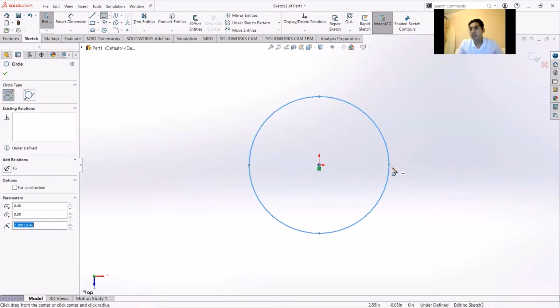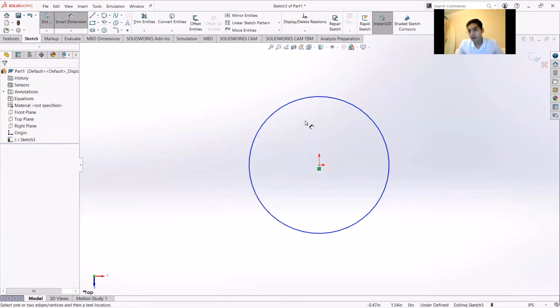So as soon as you drag it out, you can click and it'll stay there. And once we do that, you right click again, and then you go up to where those little arrow things are. This is called Smart Dimension. And with this, it'll let us set the diameter. But in general, it'll let us set distances of whatever we're measuring. So that's what we're going to do.